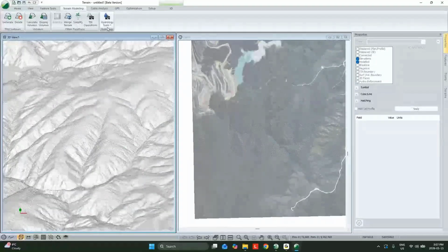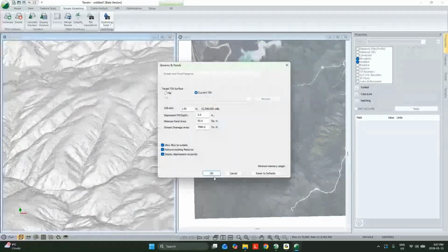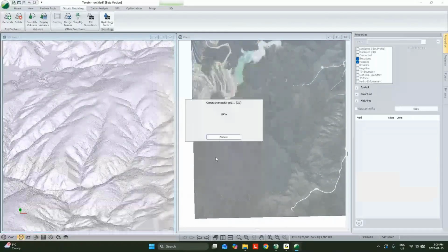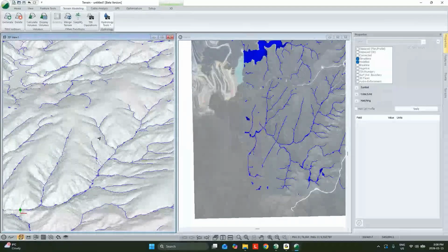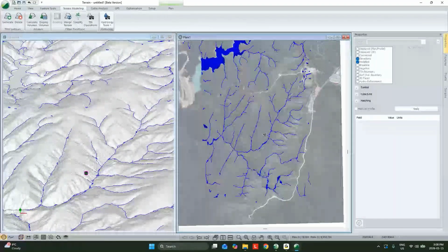So I'm going to run the hydrology tools. As we use that generative Path Explorer tool, we want to take into account that the streams cost more than just the earthworks at that location. So we have our streams generated, and we could draw in where we'd like our start point and end point to be. But in this case, I happen to know it.